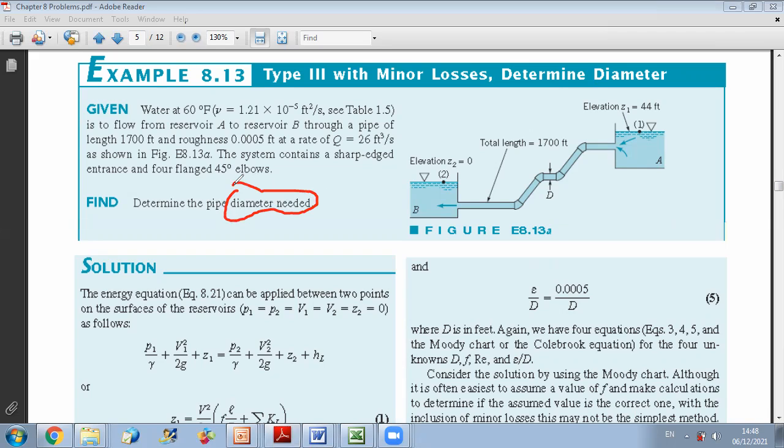So how do we think whenever we have such a problem? The first step is to write, as I told you, the equations of continuity and energy. First, because if you follow your flow as it's entering the duct, you have the same diameter. You don't have a change in diameter.